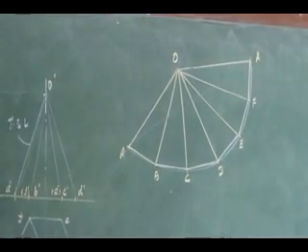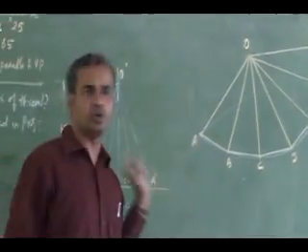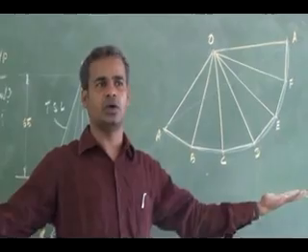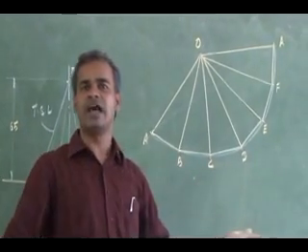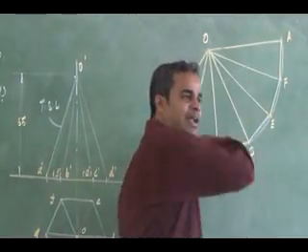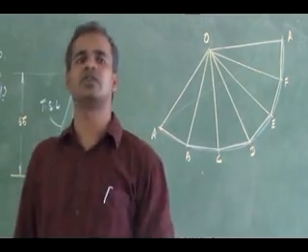Then, the first subdivision: the minimum length of thread connecting corner A to A. The minimum length I will get only in the development. Since it is on a planar surface, connecting the corresponding corners A and A with a straight line is my shortest, minimum length of the thread.